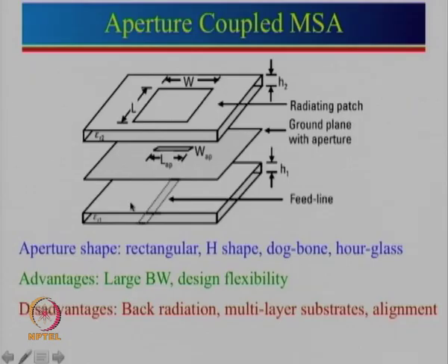The metallic portion can still remain there, and one can cut a slot over here. And on the other side, this is the microstrip line feed. Generally, this microstrip feed is again taken for 50 ohm characteristic impedance, and the length of this one here is very critical to decide the coupling between the microstrip line and the patch above. I will come to that one by one.